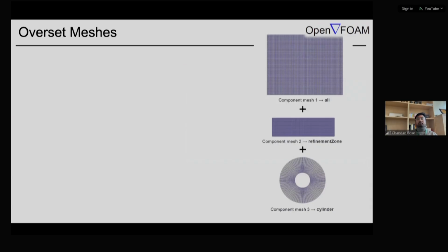Right. So again, I will come back to you if you have any questions, but due to the time, I will first demonstrate another type of mesh motion algorithm, which is called overset mesh. Now, in contrast to the morphing mesh, in the overset mesh the mesh is not deforming. There is no deformation in the mesh, which allows us to incorporate a very high amplitude motion, because our mesh will not diverge due to very high skewness or high non-orthogonality.